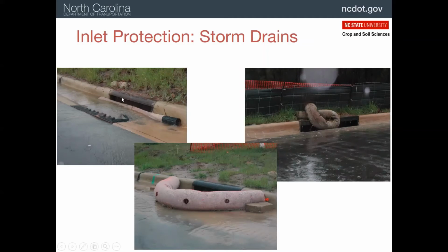This is one that is designed to be underneath the drain, or actually it's on top of the drain, but it's blocking flow through with some fabric, and then it's got the little barrier there. And there are some that actually are inserted underneath this grate that catch the sediment as it flows down through the grate. And here's one that actually blocks the flow. It just forms a dam, and then once it builds up enough, it'll go through those gaping holes there. So that's a barrier system.